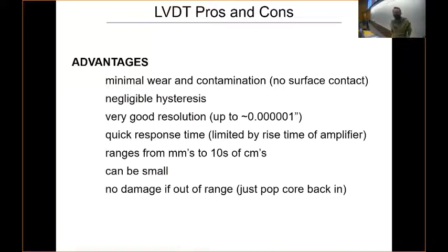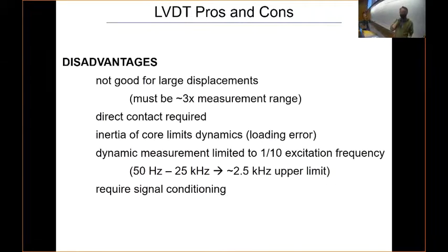They have a quick response time, just limited by the rise time of the amplifier. And you can have ranges from millimeters to tens of centimeters. They can be small, and there's no damage if they're out of range. You just pop the core back in. So lots of advantages.